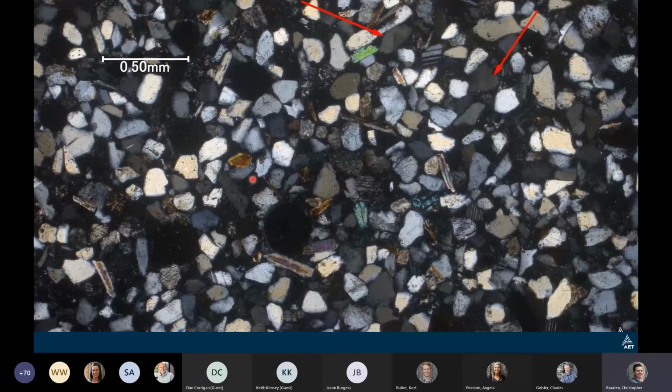And for fine aggregate, we just have to do a point count. So we're not doing rock descriptions or anything like that. We're just going through and identifying a lithology and saying granite 1, basalt 1, quartz 1. So lithologies and mineralogies. And by the time you get down to the finer sieves, like you can see here, it ends up being pretty much all minerals and no lithologies remaining. The red arrows are pointing out some strained quartz grains. You got some plagioclase feldspar in here. You got some micas. This might be a zircon or something, but you just go through and you identify those minerals and you identify anything that can potentially be harmful to your concrete, just like you would in a coarse aggregate.